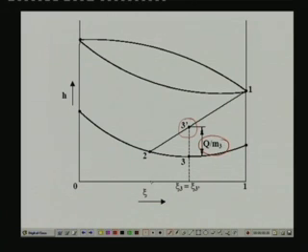at condition 3. So, if you know these two things, first find this point assuming adiabatic mixing, then this point is simply obtained by drawing a vertical line and going down by this much distance. That means this is without any heat transfer, H3 dash is the specific enthalpy, and H3 is the enthalpy with heat transfer from the system. If the heat transfer is to the system, obviously this point will move up. This is for the positive Q, whereas this is for the negative Q.